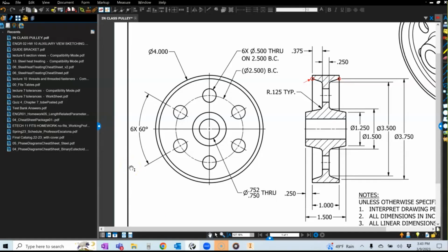And that is the reason when you see these dimensions, you go from in to out. From in to out, right? So the first thing that you see is this hole, and it has holes right here. This is a true size. I could also dimension over here because I was able to break the rule now because I have a section. And my section will allow me to dimension, as long as I cut through the whole thing. So now I go to the next feature out, the next feature out, the next feature out, the last one out, and then finally here I have the dimension of the outer boundary.